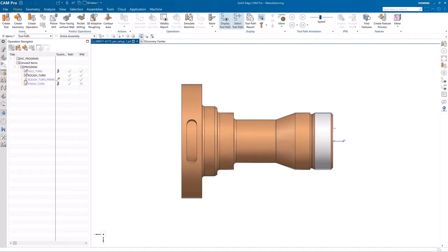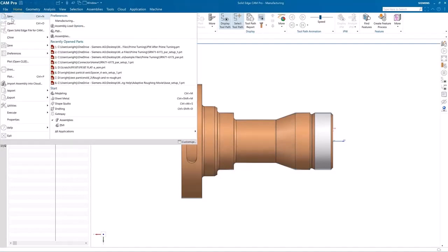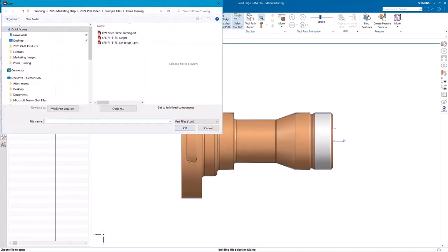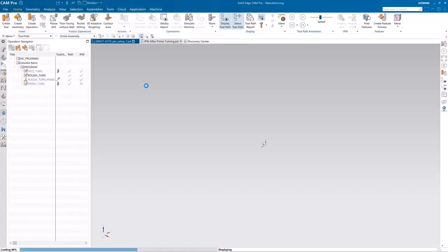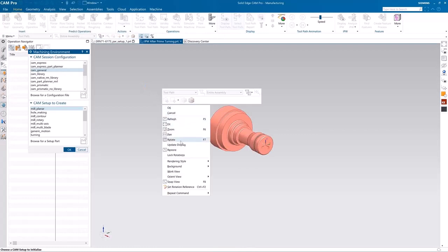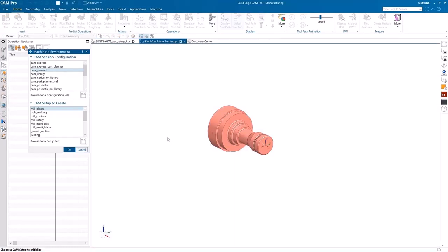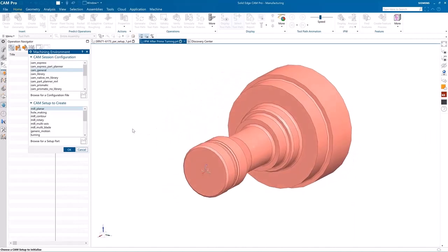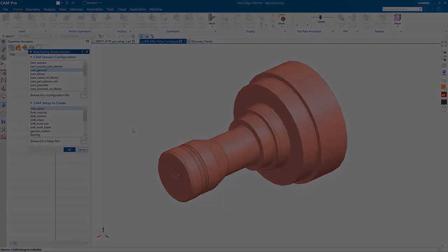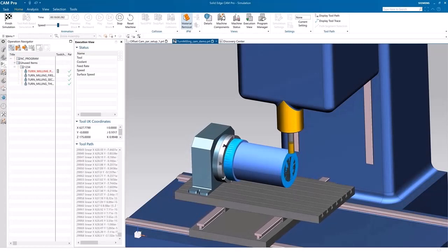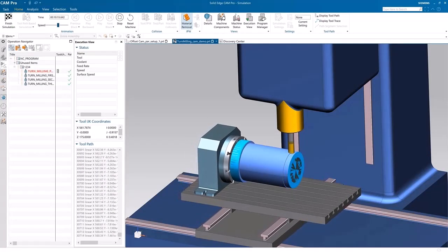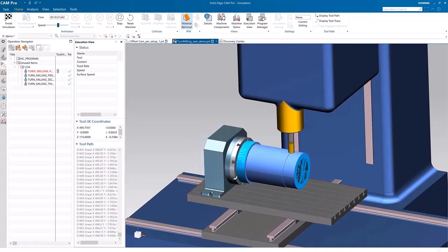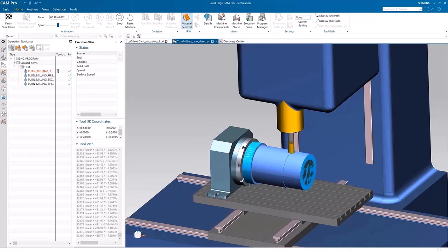Save your in-process workpieces as faceted bodies in separate files. These models can be used for future machining operations, the creation of manufacturing planning operations, or the construction of secondary machining fixtures and jigs. These in-process workpieces can be saved at any stage during the machining process, even in the middle of an operation. Turn milling is designed to easily machine symmetric and eccentric cylindrical surfaces with high surface quality, precision, and high cutting volume.